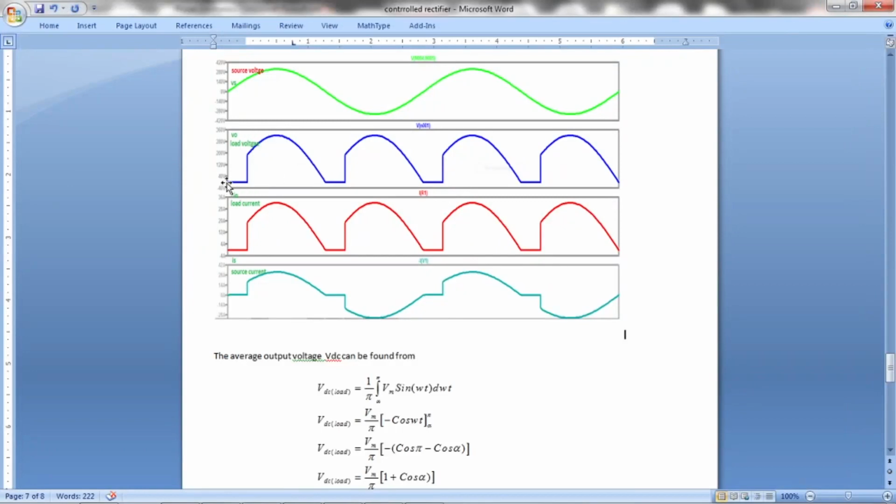This is one periodic waveform. This is the period of that. See, this is a repetitive pattern. It repeats again and again. That's why I am saying that from here to here it is one period. In a periodic waveform, if you integrate one period of that and divide that value by its period, then it gives you the average. So I need to integrate from here to here.